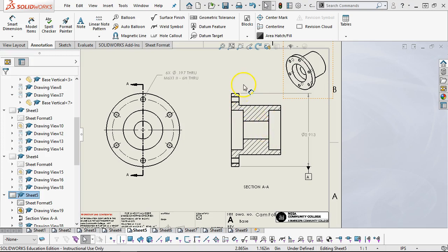The other consideration that we didn't quite, or at least I didn't show up, is a lot of times the bearing face, the inner race, will have a little bit of a raised section. It'll be a little bit proud of the dimension, and that would be something that would rub on this inside face. So there may even need to be an additional spot face in here that remains to be seen. But that's another one of those tight tolerance, open tolerance, open tolerance, open tolerance, tight tolerance. We're going through and making those determinations based on the functionality of the parts as we go.